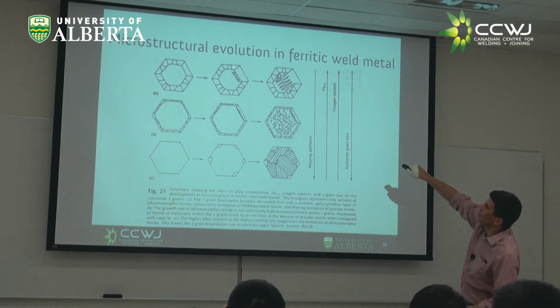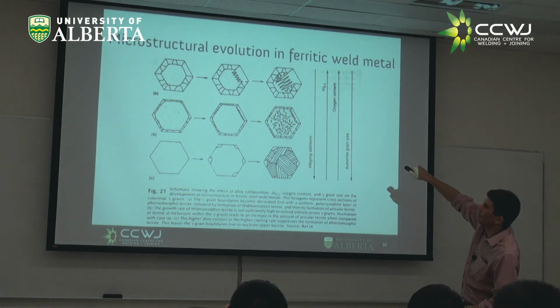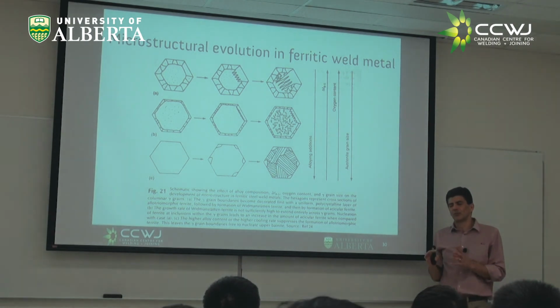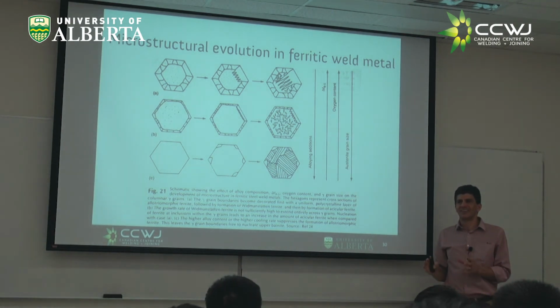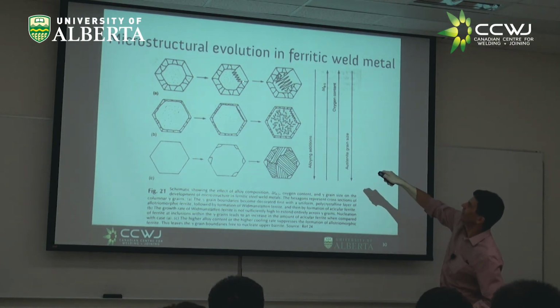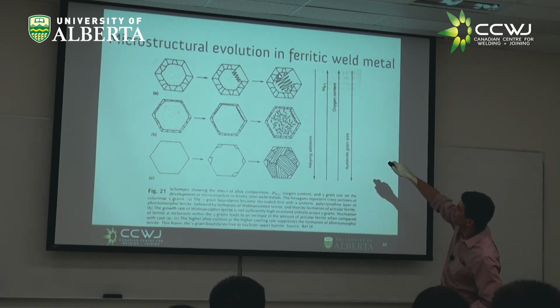And you see this thing here, this is called Widmanstätten ferrite, but let's not worry too much about it. But let's be aware, this starts to be into those things that appear as bainite in the CCTs, right? And they grow like fingers into the grain. And this little thing here, these are called acicular ferrite. They are typically good to have, right?